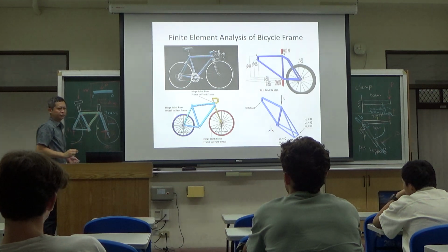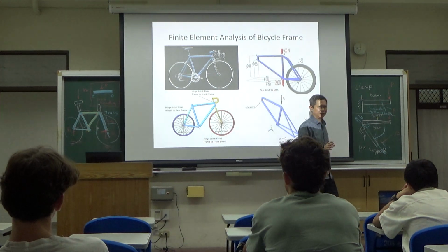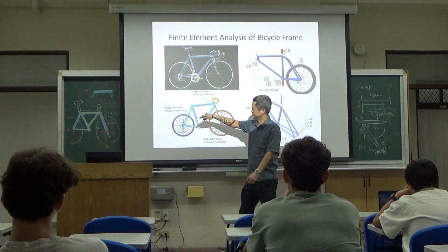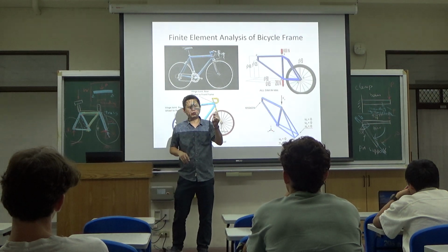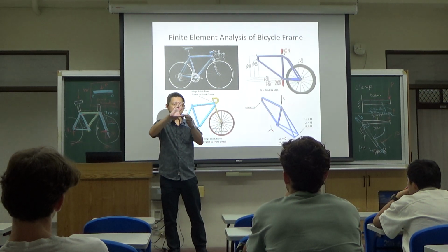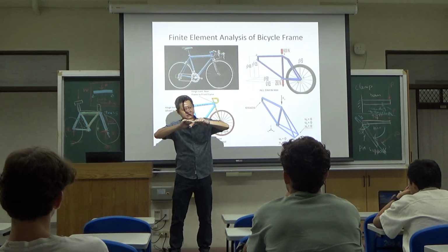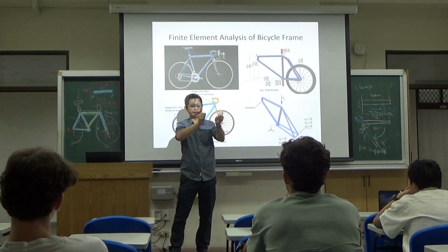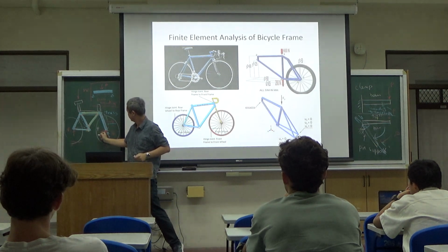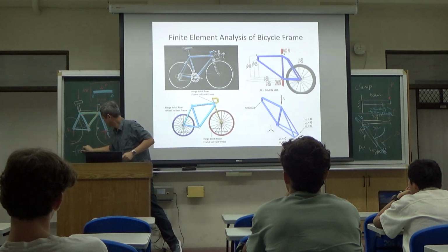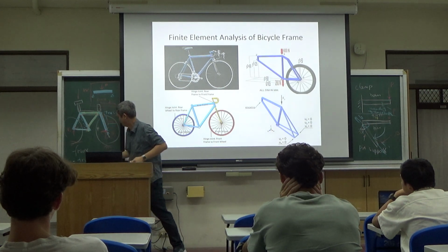Okay, so do you see that? The structure itself, whether it's a truss or a beam, is determined not by the construction, but by the loading. Take for example, if I have a chuck here, if I do the compression, it is a rod. If I do a pull, it's still a rod. But if I do a bend, then it becomes a beam. And this structure is called a frame structure because it's a combination of truss plus the